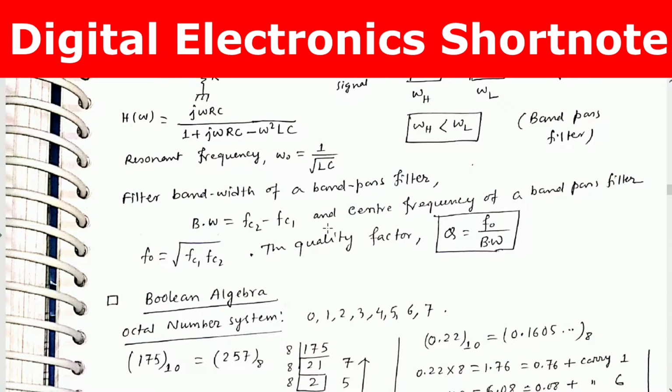Bandwidth of a band pass filter equals FC2 minus FC1, and the center frequency of a band pass filter F0 equals root over FC1 into FC2. The quality factor Q equals F0 by bandwidth.